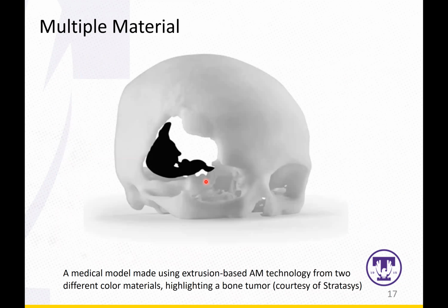Another new development of fused deposition modeling is that right now there are some printers which are capable of printing multi-material by extruding different materials using different nozzles. Like the new Ultimaker 3 machine, it has a dual nozzle, so two different materials could be extruded in a single printing process, right?